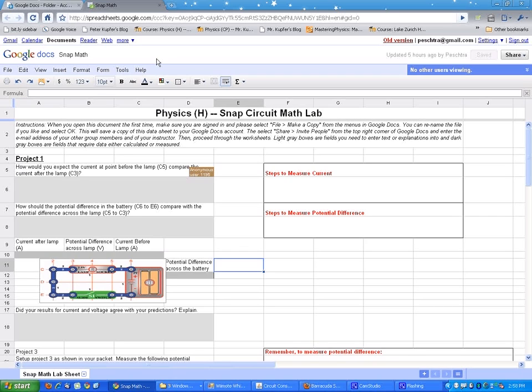Okay? Now, the first thing we're going to measure is current. It's going to be bigger than 250 milliamps, so we're going to use the hole that says 10A by it. We'll put our red probe in the 10A. And then we're going to stop for 1 second doing that. Right? Okay. So how are we going to measure current?